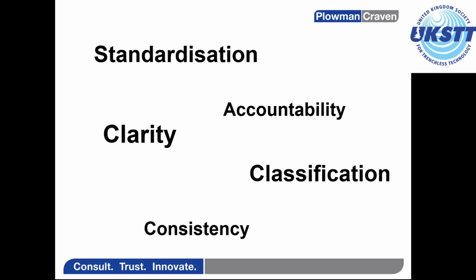It applies to the detection, verification, and location of active, abandoned, redundant, or unknown underground utilities, and the location of the associated surface features, i.e. manhole covers, utility markers, stop taps, valves. It applies regardless of where these utilities are located. It applies to utilities buried no deeper than 3 meters.